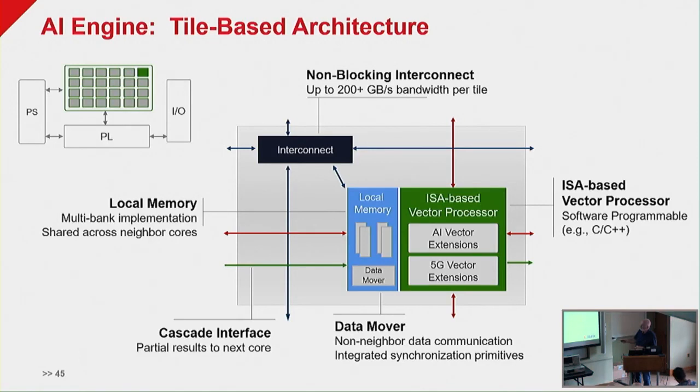And then you have local memory with each of the tiles, and this is broken into 4 such that each tile can address its neighboring tiles' memory also. So north, east, south, and west, you can dial into the memory map of your neighbor. And then if you want to do something a little less local, if you want to connect or send data to a tile at some distance from you, there's an interconnect that's exclusively associated with that purpose.